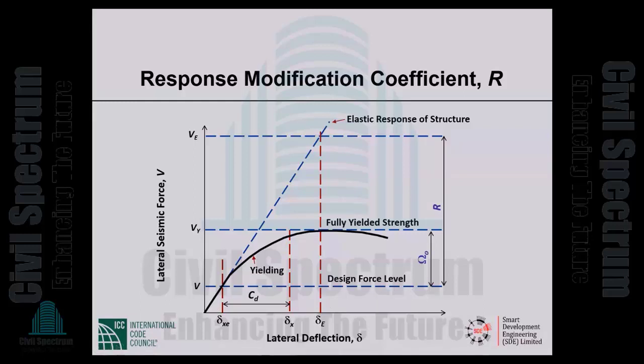If we want to figure out the very largest bending moment that can happen at that support section under the design earthquake, our estimate of that would be omega sub zero times 100 foot kips. For a special moment frame, omega sub zero equals 3. So if elastic analysis under code prescribed seismic forces gives us a bending moment of 100 foot kips negative at the support section of a beam, the actual negative bending moment that can develop at that section is 300 foot kips. That's what omega sub zero is about.